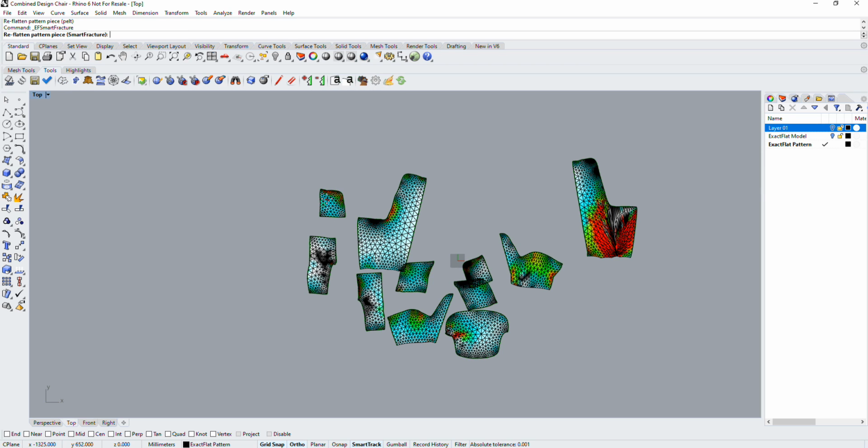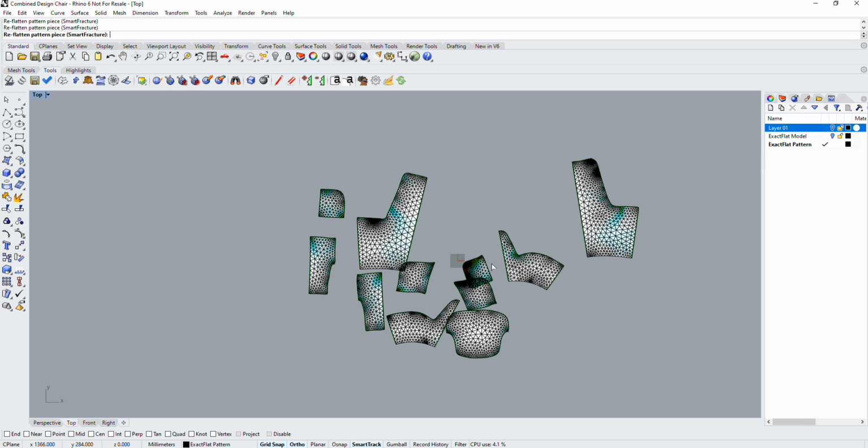Next, we're going to use our fracture tool here. And the fracture tool is like a nice smoothing algorithm. You can see that it starts the smoothing process on the location from which we clicked. And once you click it, basically, it's like spreading your hands over the pattern pieces, what pattern makers do all the time. Now we have nice de-wrinkled and smoothed patterns for optimization. These are still not yet the optimized patterns.